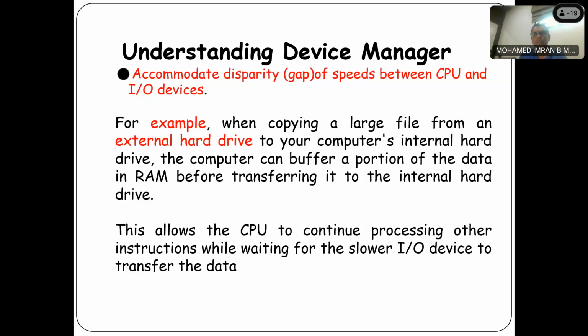So you need a device driver to transfer the data coming in into the buffer of the device driver. Then from the buffer, you download back to the internal RAM and so forth. Why do you need this buffer? Because if the CPU waits for the data coming in, it's going to take time because the data coming in is very, very slow. If the CPU waits for every data coming in, then it's wasting time.